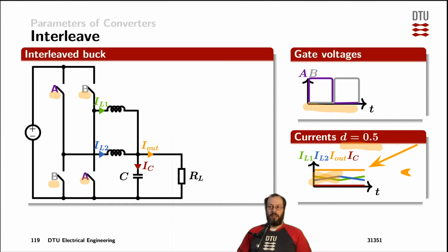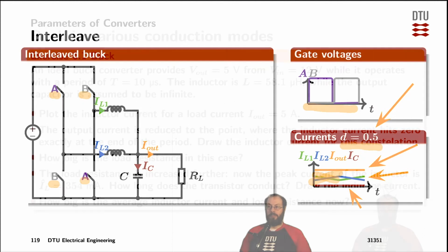as its DC current, and that the ripple currents across both of them are canceling out, and the capacitor is ending up with zero ripple. Note that this only holds for the assumption of 50% duty cycle, and the ripple current through the capacitor at the output is still reduced at other duty cycles, but is not equal to zero.